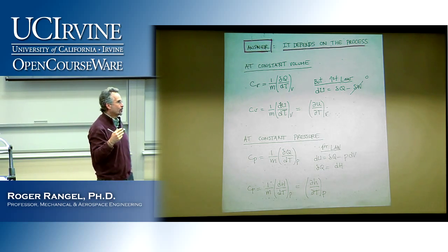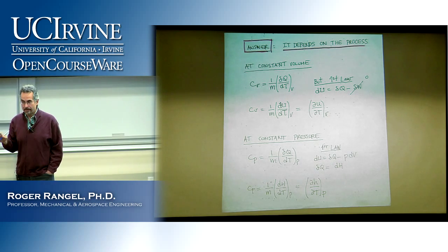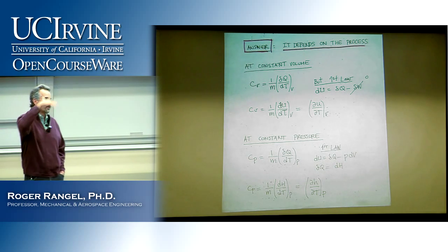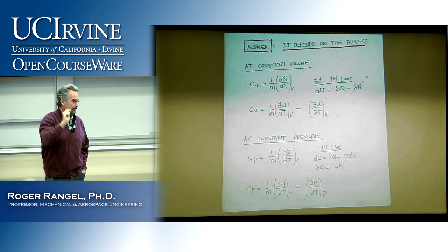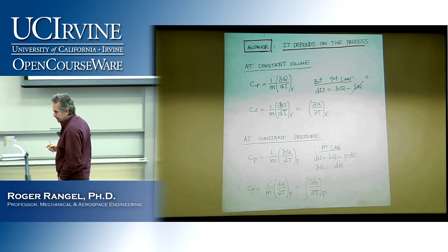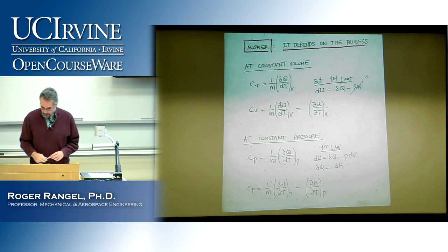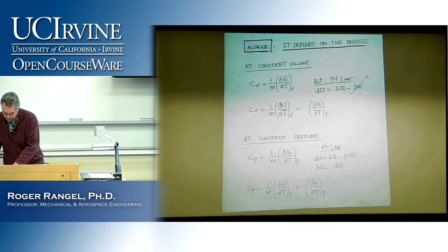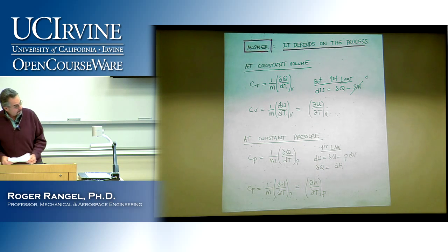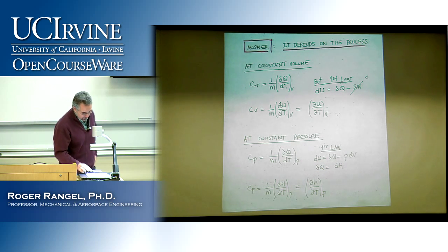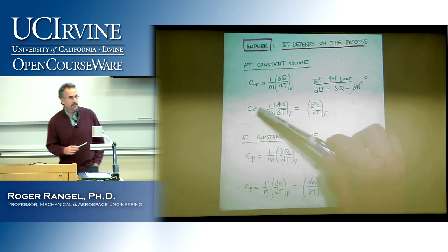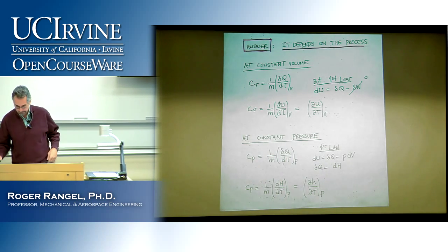And if we want to do it in quasi-equilibrium, which is our goal, then of course the pressure has to be balanced. So there is a force, there is a displacement, there's going to be work. Okay, so how can we use this? So keep that in mind. The specific heat at constant pressure is larger than the specific heat at constant volume for that reason.